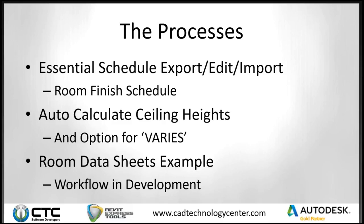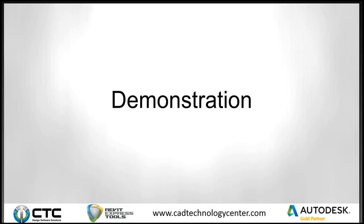So those are the 3 things we're going to do today. Basic schedule export, edit, and import. We're going to auto-calculate the ceiling heights, and we're going to do some room data sheet examples and talk about how some of that can work. So with that, let's jump into Revit and take a look at what we've got.